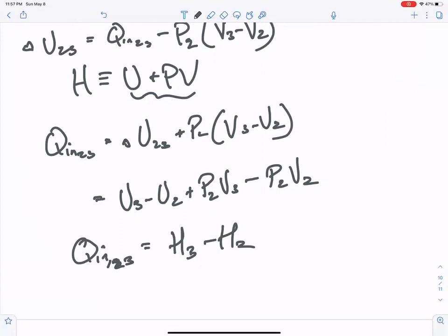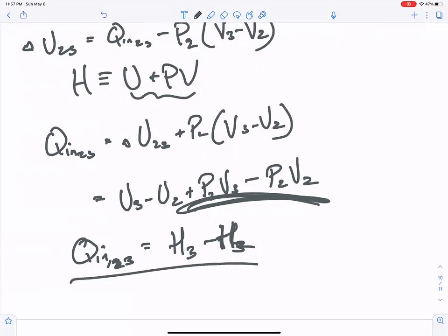So you can express it. There is a work term here because a boundary moves, so it is work, but it is also a PV term. Sometimes this PV term is there without work. Sometimes this PV term is there with work. Either way, mathematically, that's what the enthalpy term captures. So in this diesel cycle, constant pressure heat in with this volume change can be expressed in terms of this enthalpy change, even though it's a closed system with no reactions. In this case, it's because the boundary moves. That's why the enthalpy comes into play, and the book just skips that many times.